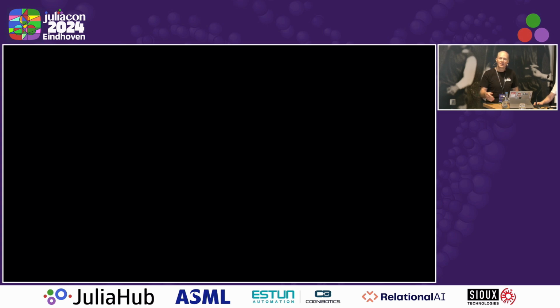So yes, I think there are opportunities that JSML can take advantage of. Being pretty knowledgeable about Modelica as well, what I tried to do was take what really worked well in Modelica and incorporate that. So you spotted that with the annotations. Although those are JSON annotations, I should point out. JSON is now ubiquitous. Everybody can read and write JSON. Modelica has its own structured data syntax. There's just no reason to have that now, so we switched to JSON. We use SVG for graphics because there's no reason to use something other than that. Those are examples of how we tried to modernize some of those concepts.